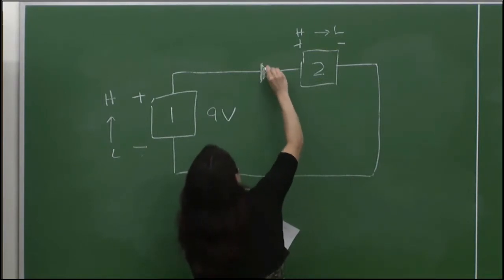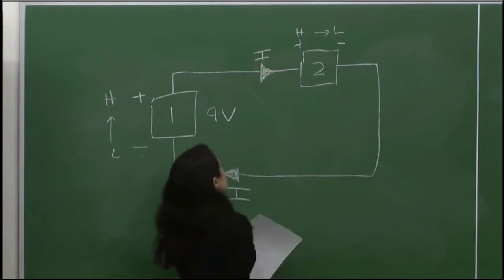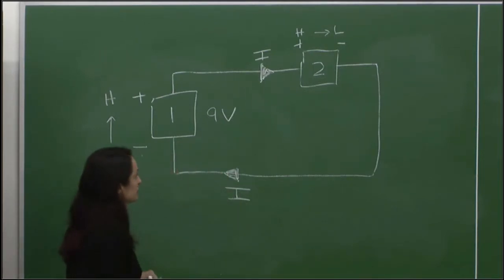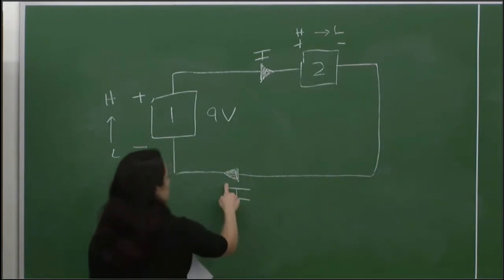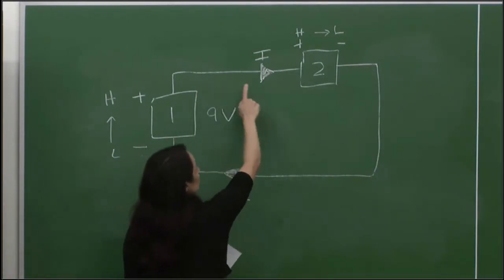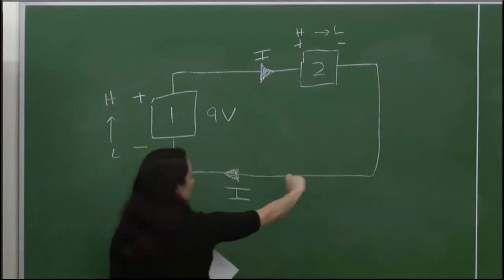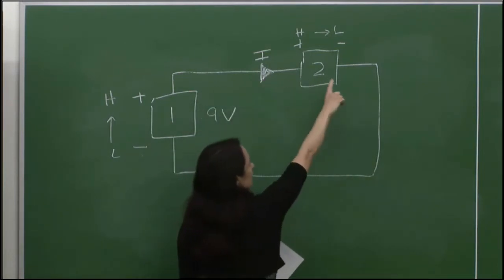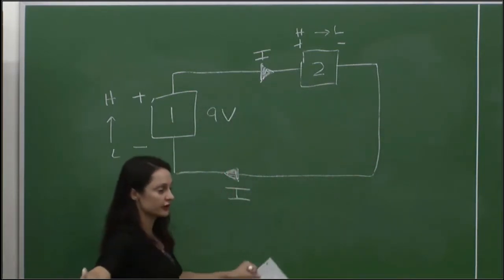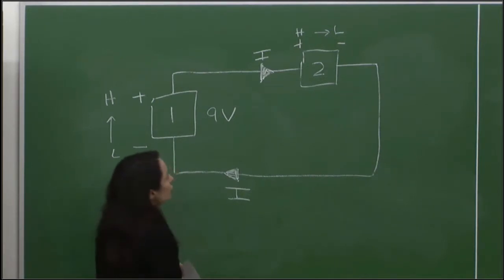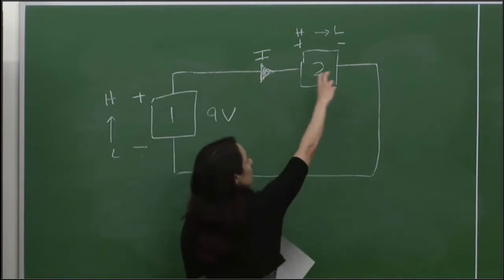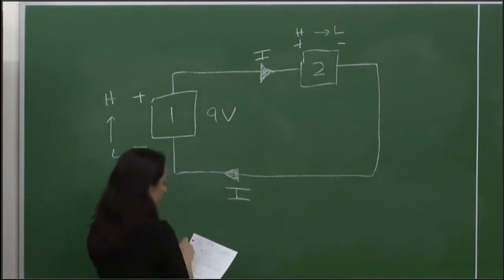Right now, this circuit is something called series, and we'll talk about series and parallel later. We have a single loop. If a current is flowing here, the same current is flowing through all of these. We're not changing that current amount. There's nowhere for that current to flow off or go somewhere else. And this we'll talk about a little bit in the water analogy. You kind of think of current flow like water. There's only one pipe going around here, so that same current's flowing through.